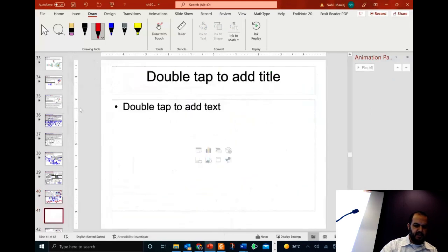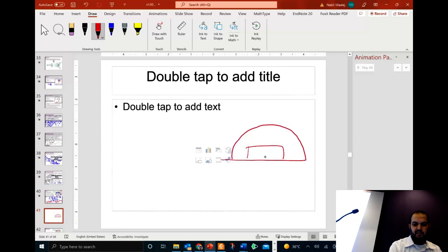So we put the chamber inside a dome, and we have a very strong strobe light inside it, and we have photovoltaic cells all around. This dome is a semi-spherical dome, and there is a platform. It's totally dark. When we turn on the light, we detect the light that is coming out of this chamber. From the pattern of the light, we determine where there is leakage and where there is no leakage.